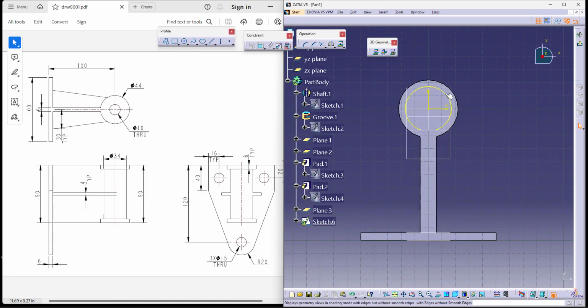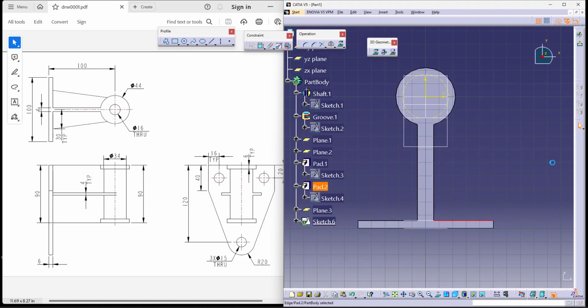As you can see, now I'll just make it concentric. Yes, and now I'll be using this one as well as my reference. Now I'd like to make a line. As you can see, it's actually a line which is starting from here and ending over there, with certain dimensions. So I'll begin and end. It has to maintain tangency at this location. So let me maintain tangency and then give a dimension from the center to 30.